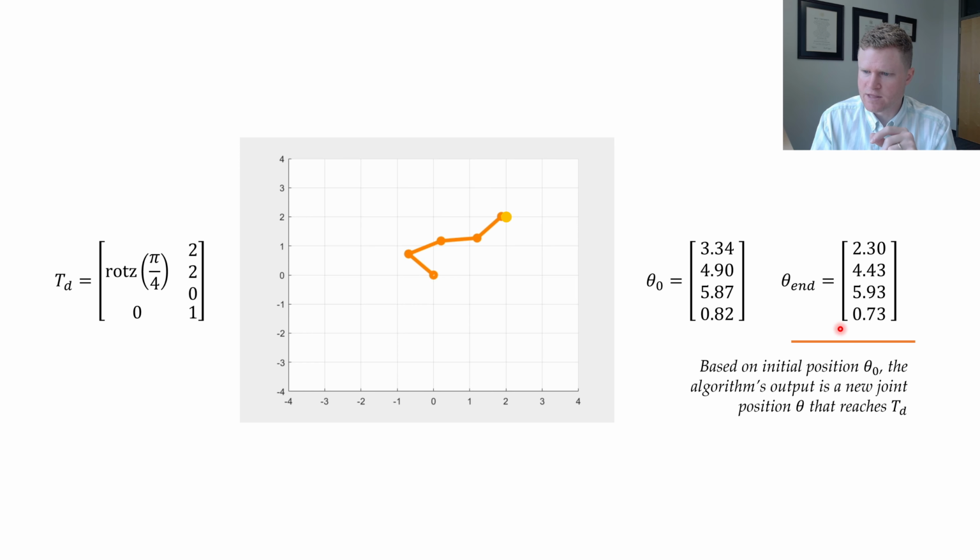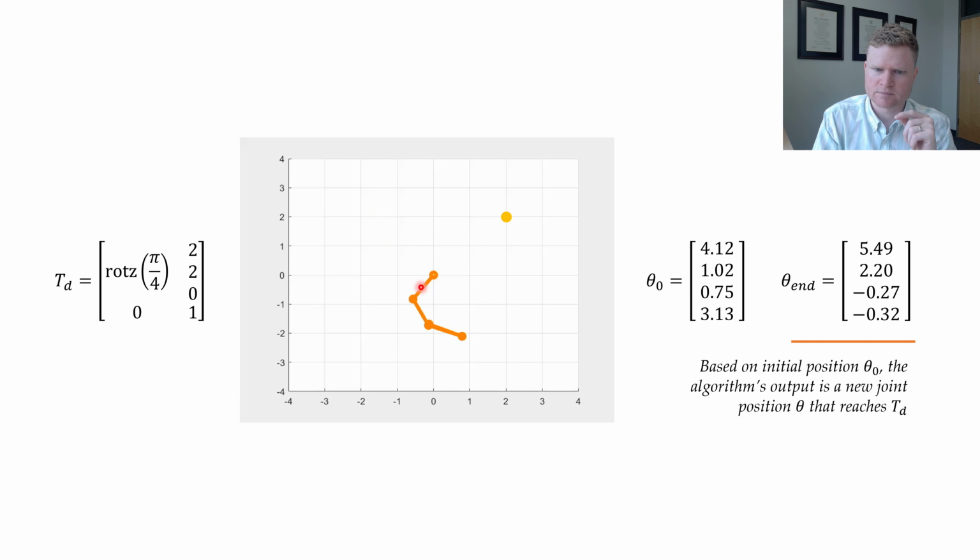Here, I've got this joint value, and you can think about this maybe as an elbow up solution. Whereas in the previous slide, if we go back to it, sorry, one second. Here we go. If we go back to this slide, you might notice that the robot has an elbow down solution, and it has a different vector right here. So this goes back to one of the challenges of inverse kinematics. We found two valid solutions, but they're different.